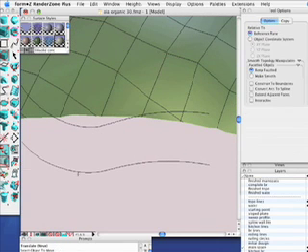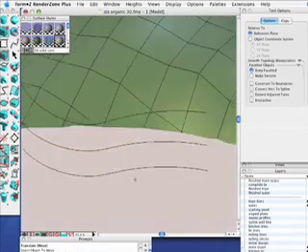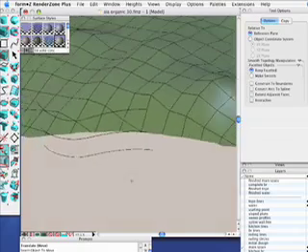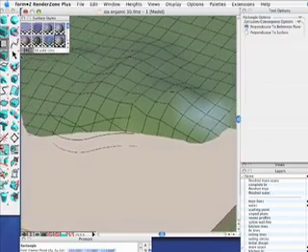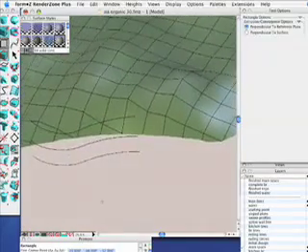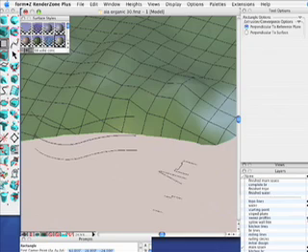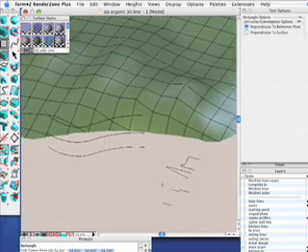And I do need to make a copy, so let me set one copy there. And I'll just pull that up about 12 feet. Alright, so I have 3 lines that follow the shape of that original face now. I'll turn on some profiles that I have pre-drawn, and I'm going to extrude them along a path. You can see right here I'm extruding in a straight line.